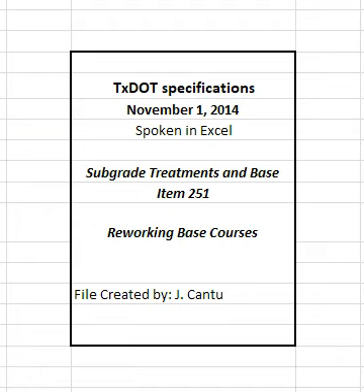Measurement is further defined for payment as follows. 5.1 Station. By the 100 feet station measured along the center line of each roadbed. 5.2 Square yard. By the square yard of existing base or pavement in its original position. When square yard measurement is used, limits of measurement will be as shown on the plans.